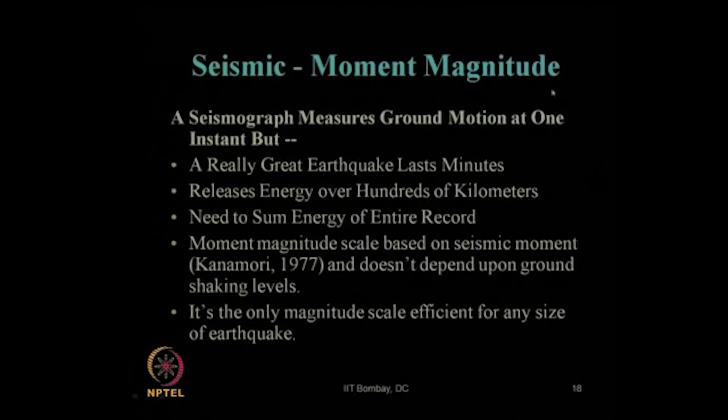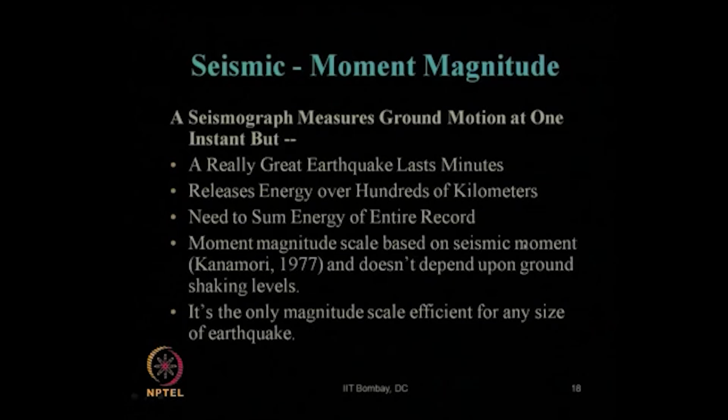Now, coming to the best magnitude scale, which is called seismic moment magnitude scale. So, a seismograph measures ground motion at one instant, but a really great earthquake lasts for several minutes even. So, it releases energy over hundreds of kilometers. So, we need to sum up this entire energy for the entire record period. So, that can actually estimate what is the magnitude scale. If we estimate the total energy which is getting released for over a couple of seconds or even minutes, am I right?